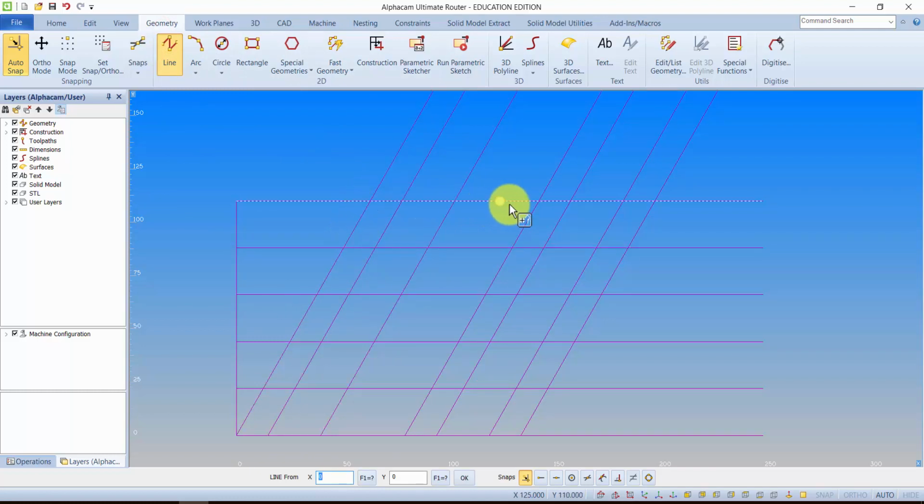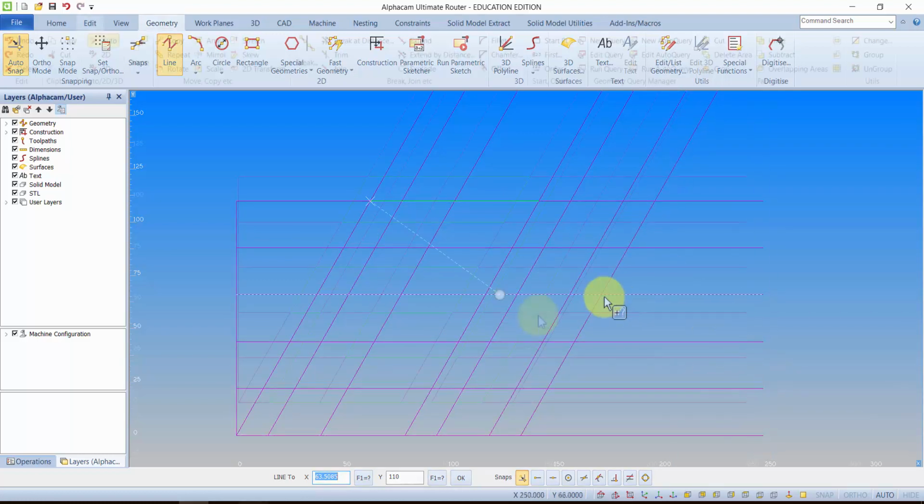The reason I choose not to do this that often in AlphaCam is the intersect tool isn't actually that quick to use. If I want to get the intersection of those 2 lines there, I need to get down here and press intersect, and press that line and that line. And then intersect again, and press that line and that line, and it just takes that little bit longer. So in AlphaCam, I much rather trim out the excess in the background rather than going over the lines with this. But please yourself, just take a moment there to trace over the areas that we have already, and I'll show you how to do the other portions in a moment.